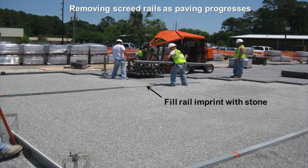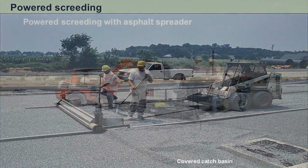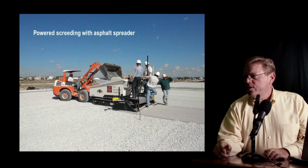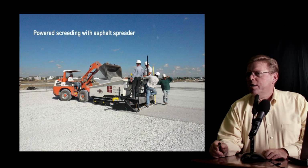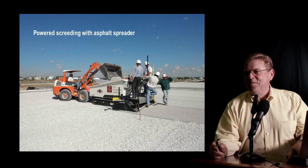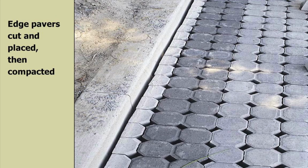This guy's touching up the bedding layer with a rake. Fill where you pull out the rail, fill that back up with bedding material. You can use powered screeding for larger, more linear applications. And here's using an asphalt spreader to spread that bedding layer. It doesn't usually take 5 guys to do that. This was the guy's new equipment, and he invited everybody out to take a ride on his asphalt machine, but very economical way of screeding that layer of base.